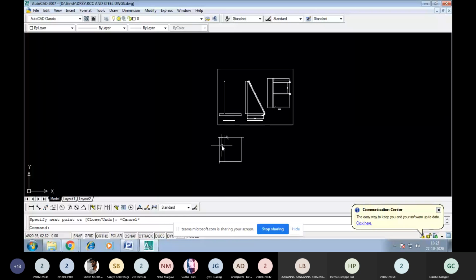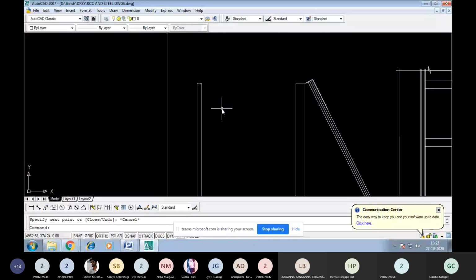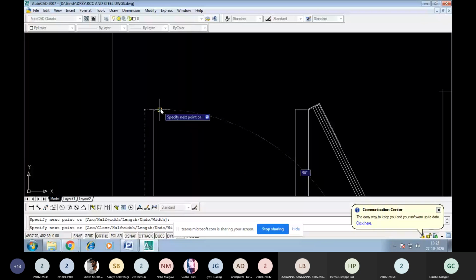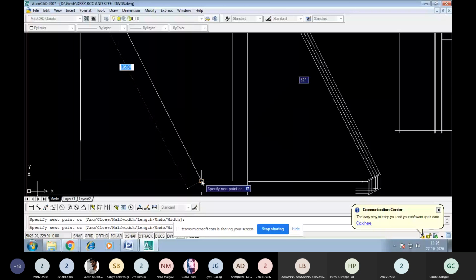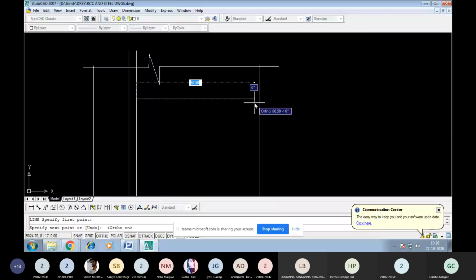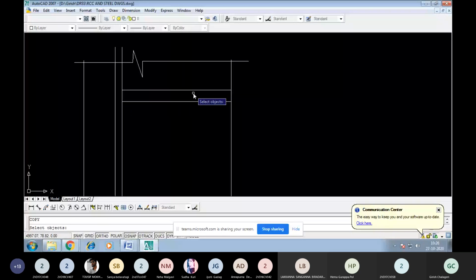Now, how are we going to draw the counterforts? Counterforts means I am going to take a triangular shape with a length and height, taken in this fashion. So this is one component I have taken, and at certain intervals I am going to draw like this. A concrete structure will be built in this fashion, at regular intervals of about 3 meters from center to center.